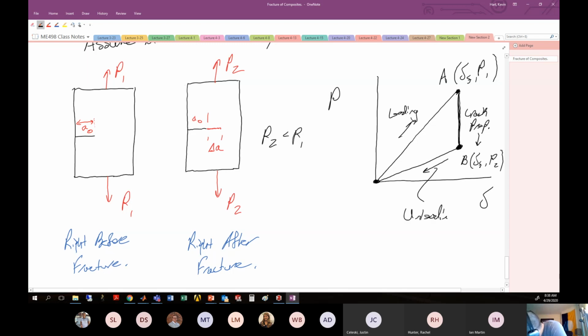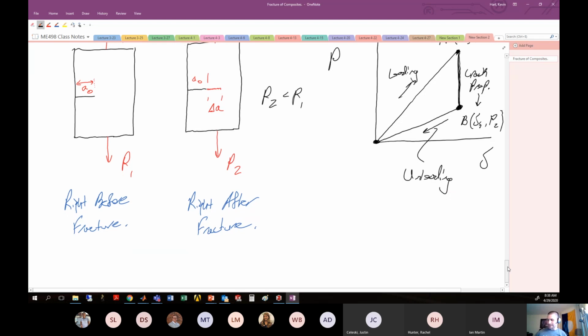So even though it's got this massive crack that's formed, there is no energy associated with plasticity that we put inside the sample. So you load this, a crack happens, then you unload, it will still go back to its original position, but you have this massive new crack inside of it. So this is the general schematic that you should have in your head of what happens with a single fracture event.